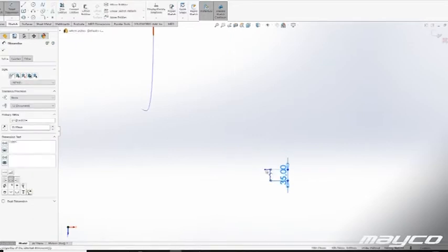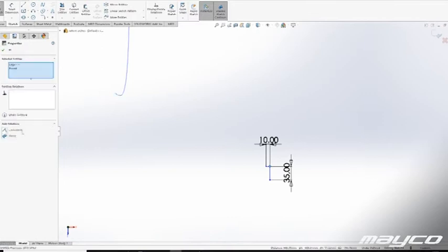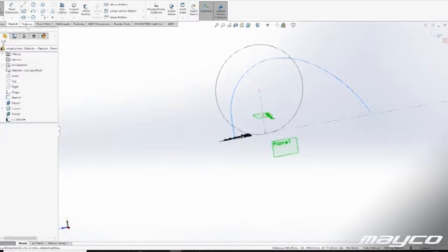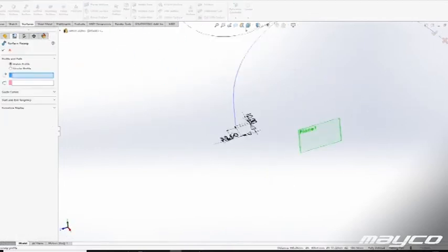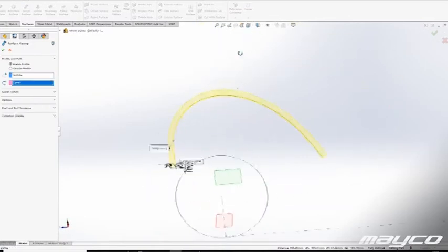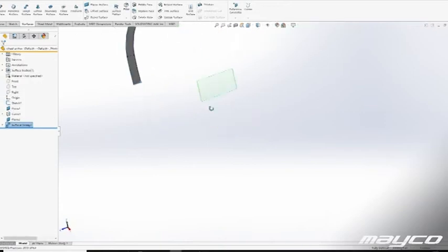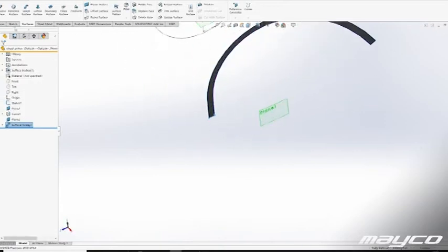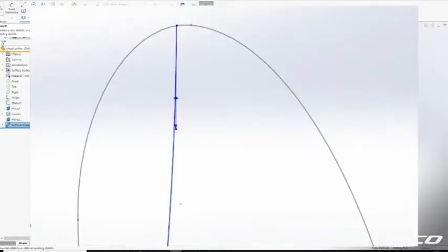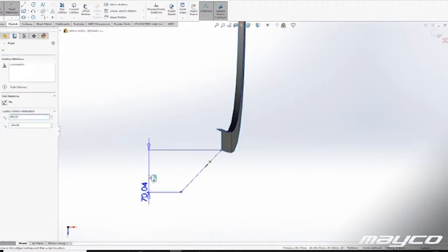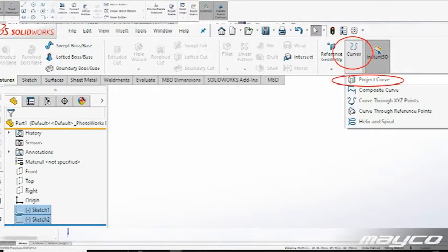Just like with modeling bodies, you can also use a loft. The first thing that I do is I take a sketch from the design that I want for the line of the wheel arch. Then I make a sketch on the front plane, and based on that sketch I let the software combine those two sketches.